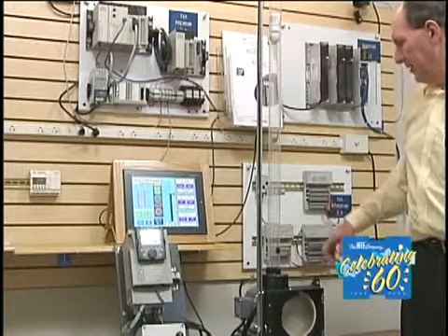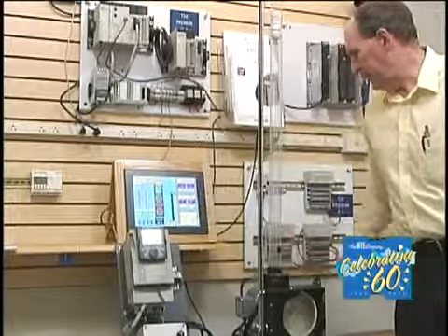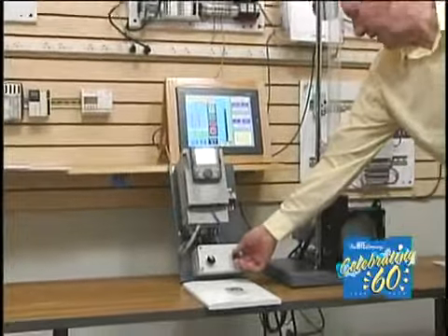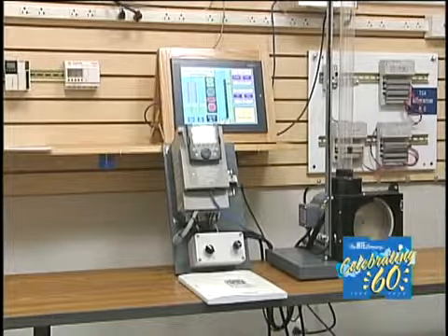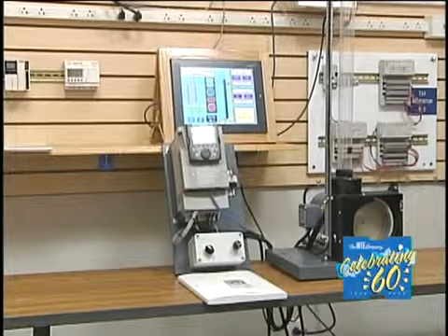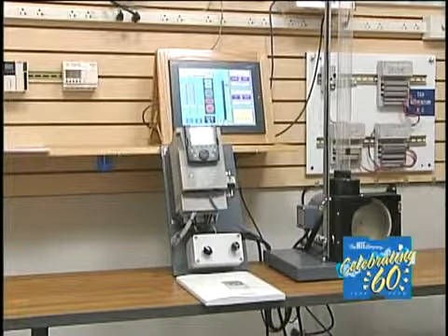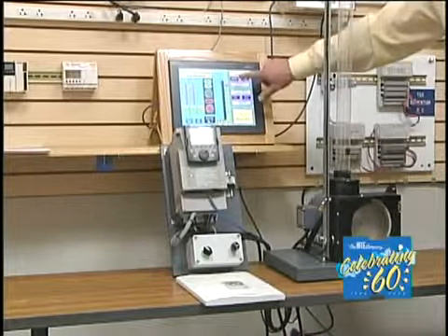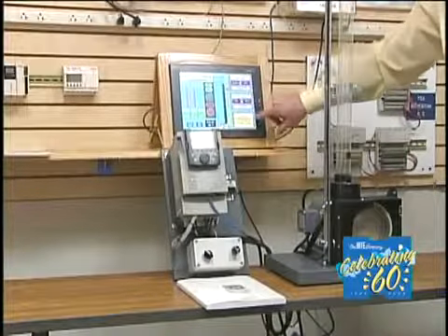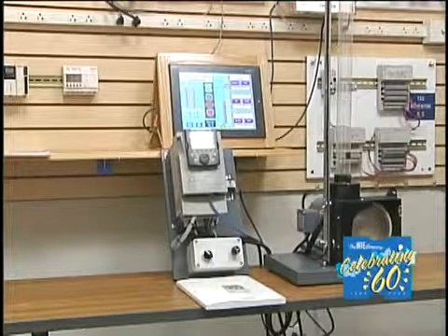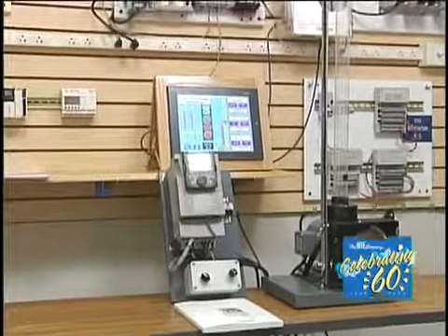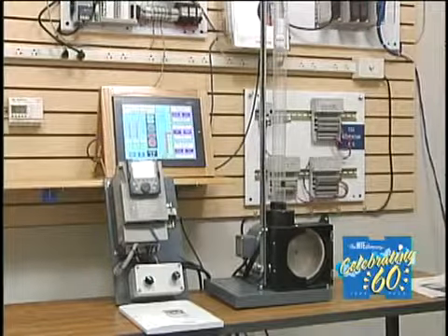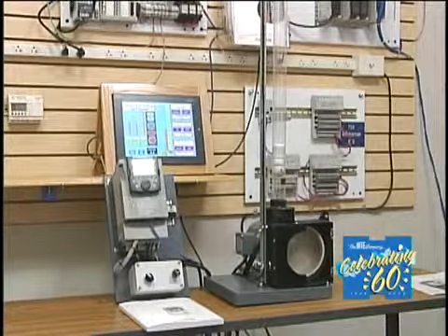And then, as far as mode is concerned, we'll hit manual here. Now our speed pod is actually a speed pod that has direct control of the speed of the drive. The drive is not using the PID controller at all for speed. Speed reference is coming directly from the speed pod. We'll put everything back on network command, PID mode. And our set point will come from the network. It's back where we started. Shut her down here. That's our demonstration.